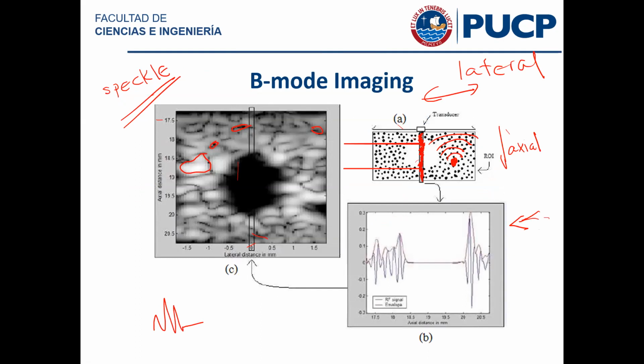If you have a transducer that produces a pressure field that is mainly limited to that very narrow red region, then when the transducer is sitting in here, it's not going to get signal from, let's say, that X over there, because it only sees things that fall within that red fringe. It doesn't sense things that are outside of it. So that X is invisible to the transducer.